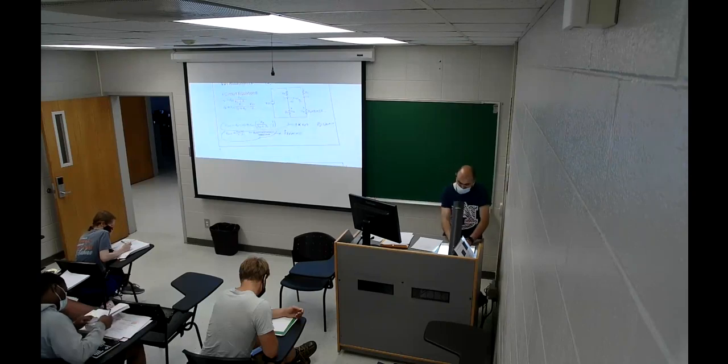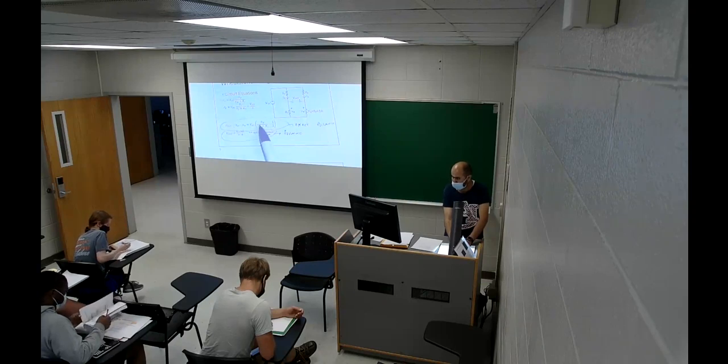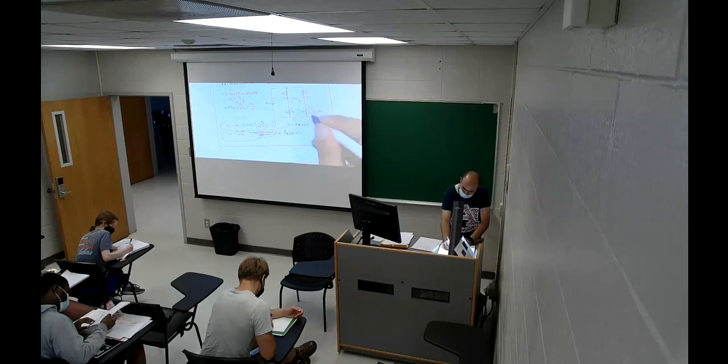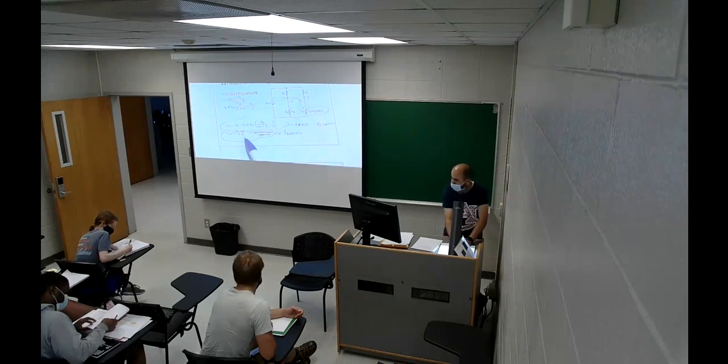You need to write this in your note card. They say V out equals VDC times Rx over Rx plus Rf minus 1/2. So V out equals VDC over 4, if I assume Rx equals Rf plus delta R, so I can find delta R.